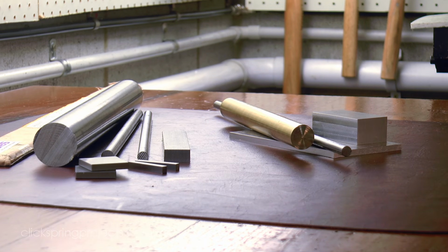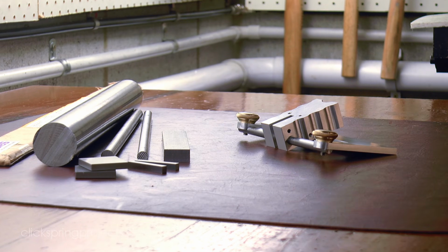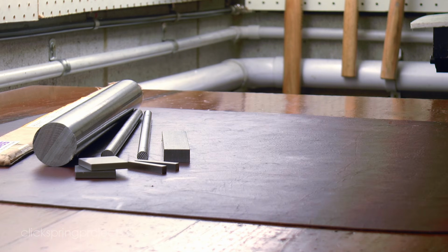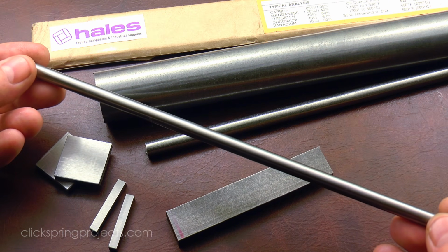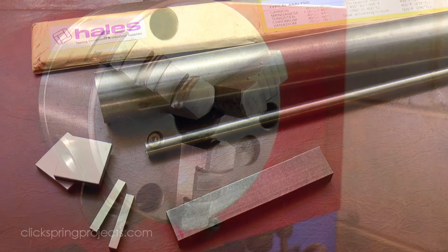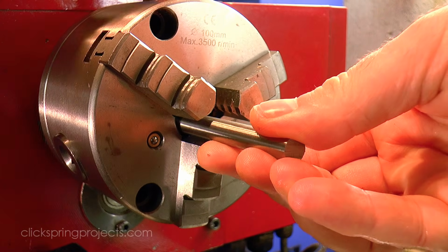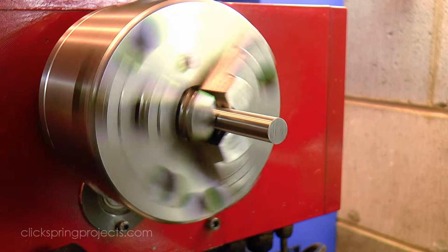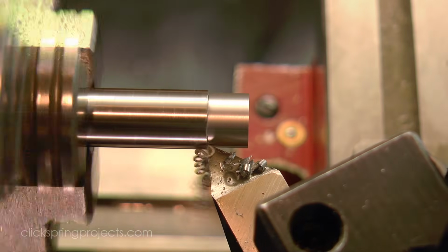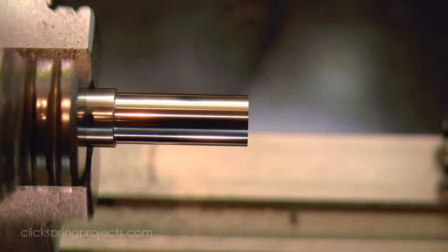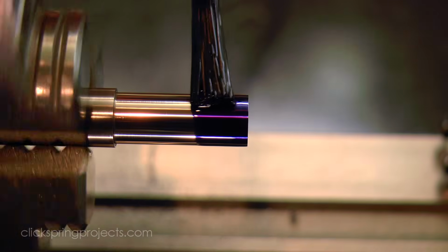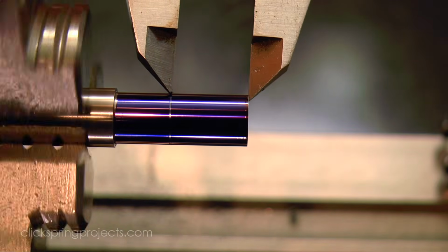Now the sharpening tool from the previous episode is a light-duty hand tool, made from relatively soft materials like brass and mild steel. Our cutters, however, are going to have a much harder life, and so need to be made from a much tougher material. And there are several heat-treatable steels that could fit the bill. But O1 tool steel tends to be the go-to candidate for this sort of job in the home shop. Like most of the high-carbon steels, it's relatively easy to work in the annealed state, so we can form the delicate shapes that we need using common home shop tools. But its big plus is that it's so easy to heat treat using the standard home shop method. No special gear is required, just a propane torch and a bucket of oil.